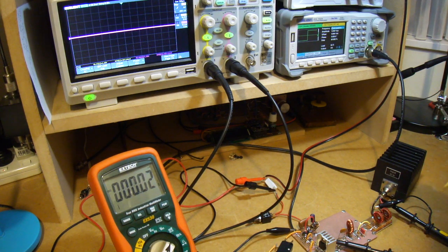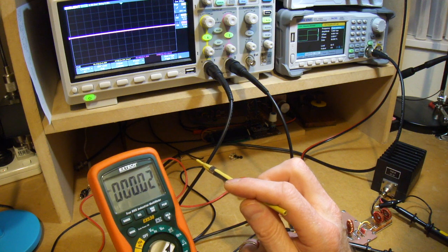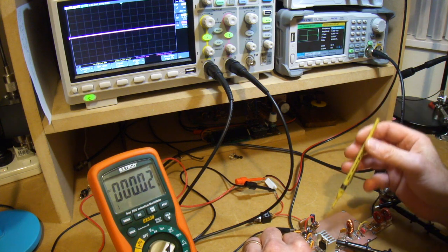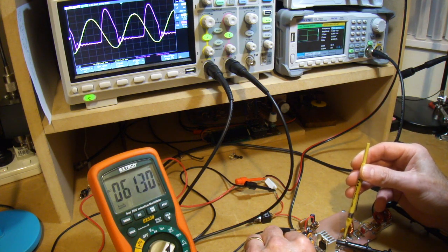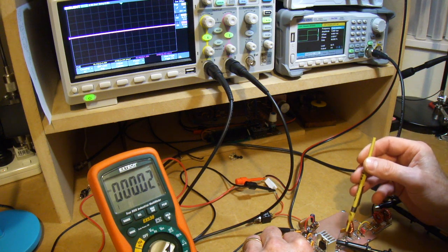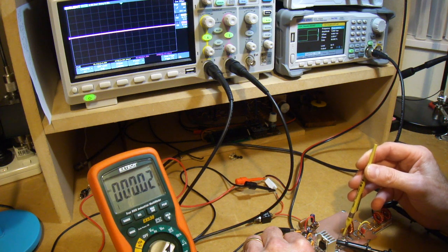which basically got things resonating nicely, because before I did that, I found for whatever reason that the power I was getting out was in the region of 2 watts, in fact less than 2 watts. It just wasn't performing at all. Having done what I've now done, with that 220 plus that 50 picofarads in parallel, which arguably comes up to the same value as the design spec,